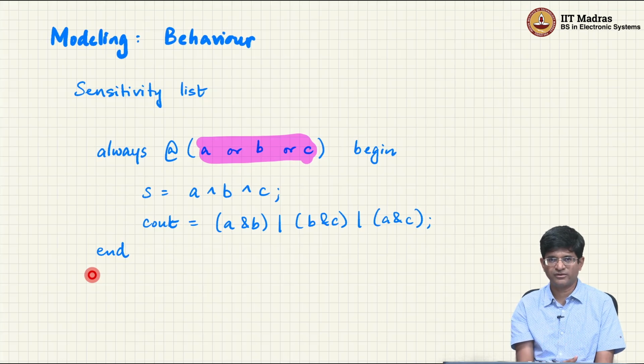I could have other kinds of register transfers where I might have, for example, a register file in a CPU where I take two outputs of the register file, perform a computation and then transfer the result back into another register. Each of those kinds of expressions or computations, the way that they are described, that is what constitutes RTL or register transfer level. We are breaking our entire design down into simple modules or simple blocks that constitute moving data around between registers.